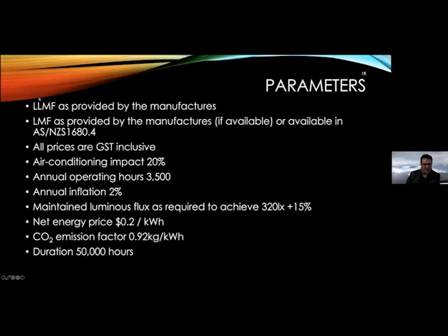When analyzing that, I have used the lamp lumen maintenance factor as provided by the manufacturer. And then I use the luminaire maintenance factor as provided by the manufacturer if it's available, or if it's not available, again, I refer to that particular table from the 1680.4 standards.